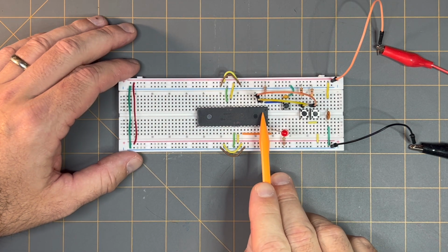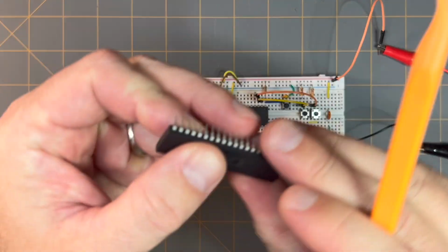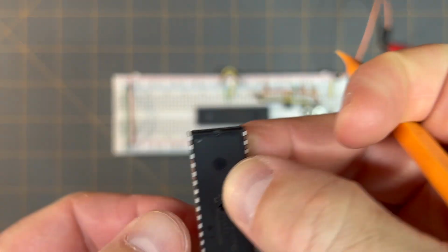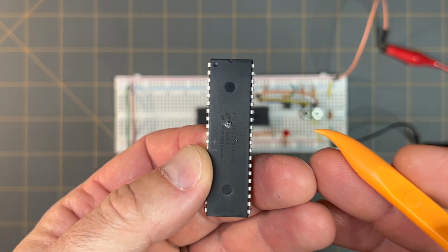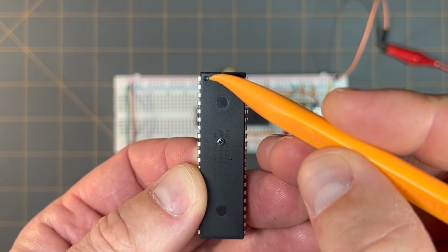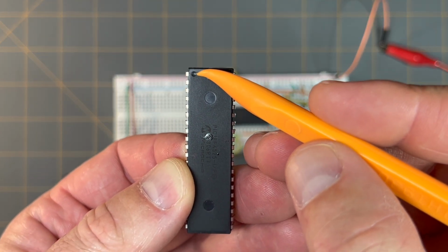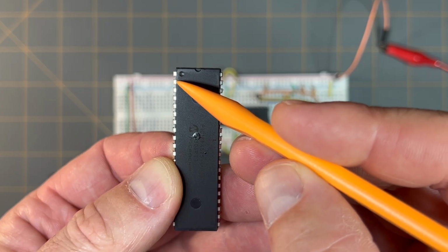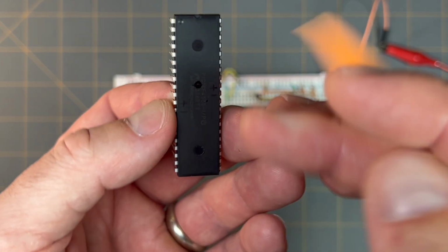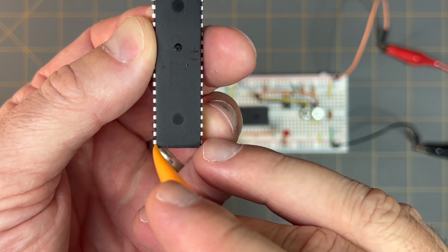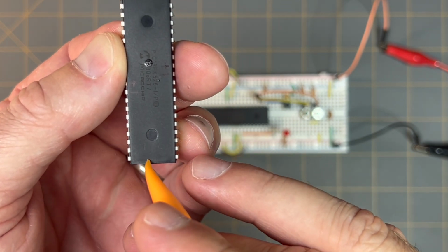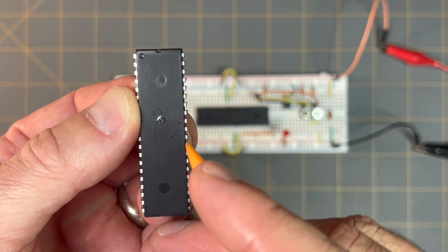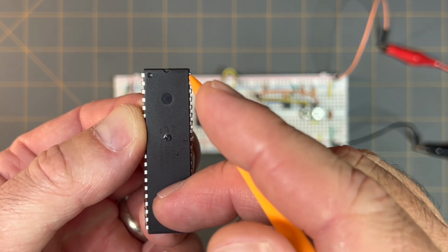And when you're doing this, if the PIC is faced in this direction towards you, with this dimple in the top left hand corner of the PIC's body here, that indicates pin number 1. So this would be pin number 2, pin number 3, all the way down to the last pin on the left side, which is pin 20. And then directly across from there is pin 21, pin 22, and then it proceeds up the right side of this PIC up to pin 40.